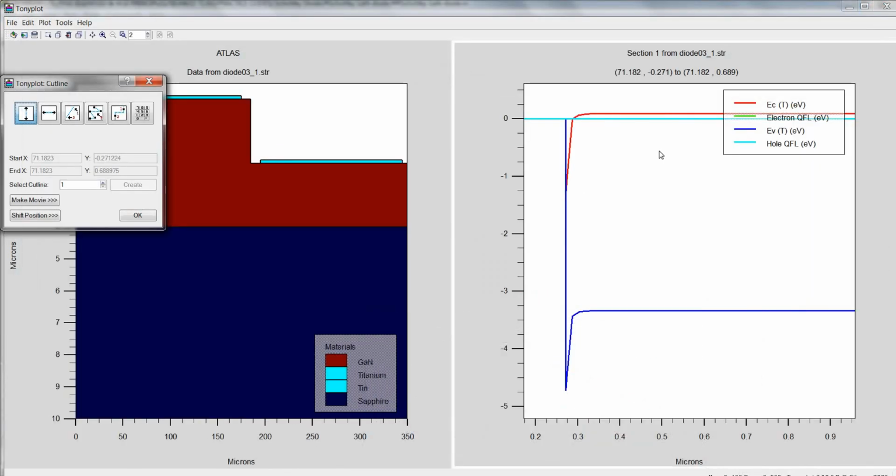as this is metal deposited on N-type semiconductor, we are mostly interested in looking at the conduction energy level behavior. And now we can see here is our Fermi energy level, which is constant throughout the structure under thermal equilibrium. Now you can see that we got a really small barrier over here for electrons to flow from the metal to semiconductor.